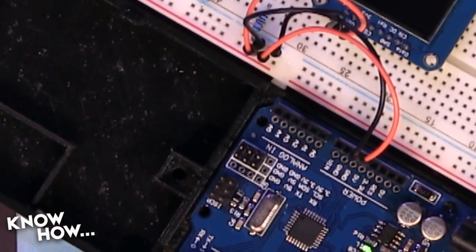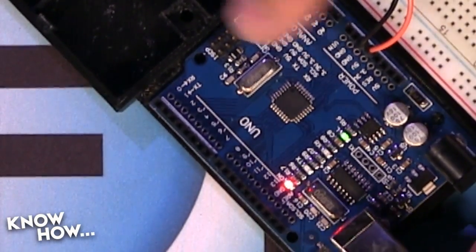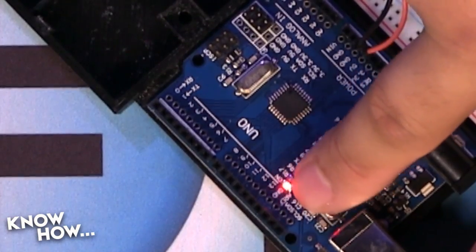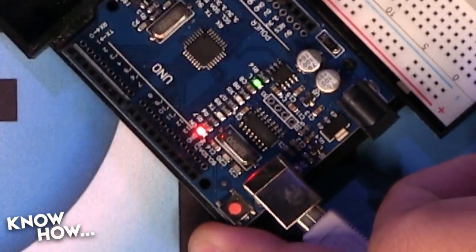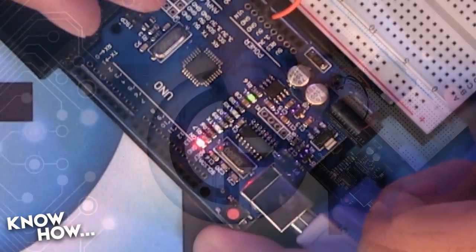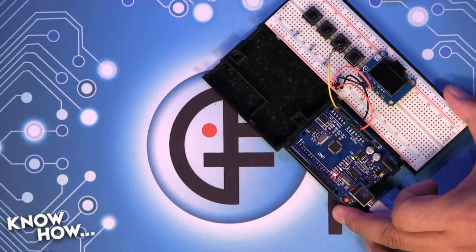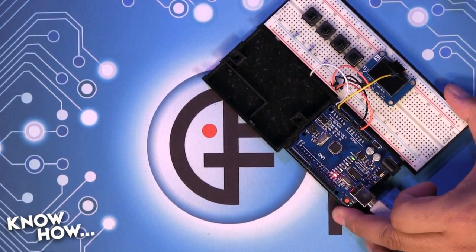Now, if you want to, you can actually pull it from the other side right there. Notice how these are actually labeled SCL and SDA. That's just, it's the same. They just have it on both sides of the board. Okay, so I'm going to say my data pins are always going to be yellow, and my clock pins are going to be white. And again, this is where it helps to have a bunch of jumpers that are color-coded because it's going to get real confusing once we get a lot of these jumpers in here.